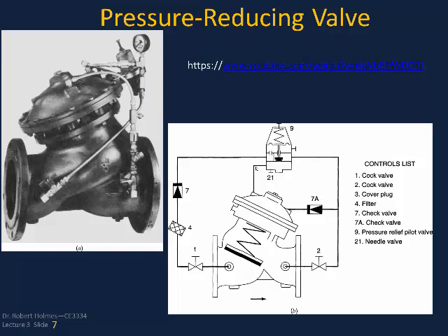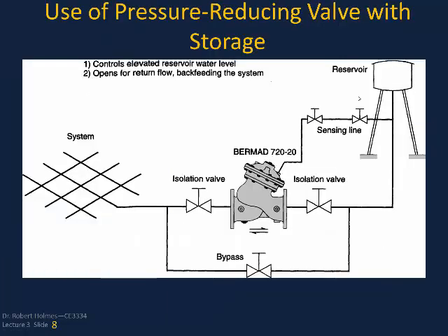This is a pressure reducing valve, which has taps here that you measure pressure at various locations through the flow, and through mechanical means it can open and close the valve to a certain degree, where it drops the pressure down on the downflow side, where it can be used without, like I said before, blowing out the commercial or residential systems. There's a nice YouTube video here that you can view that explains further the pressure reducing valve.